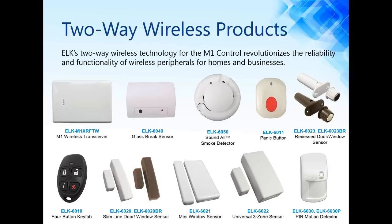Also, if anyone has recently heard about other manufacturers of wireless technology, they use a single band frequency. The ELK two-way wireless is frequency hopping, which means that we spread the spectrum between 902 and 928 megahertz. So we're not constantly transmitting and receiving on one single frequency. We're jumping around, which makes it more difficult to try to detect what frequency the sensor is on. It also makes it more difficult to jam our sensors.